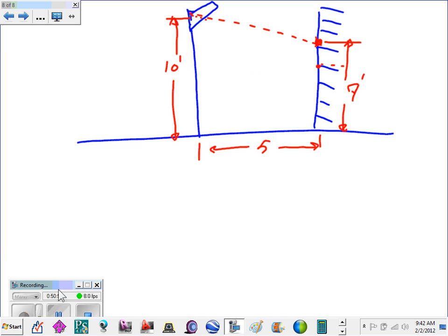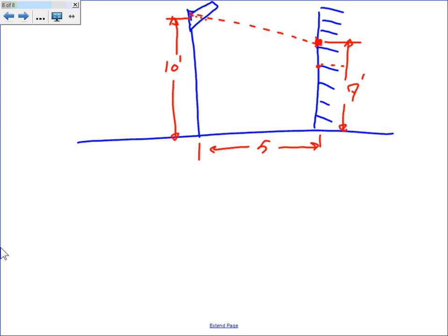For this example, this is the same lighting fixture that we talked about before, the same characteristics, everything is the same, except we have a billboard and we want to light that billboard with this floodlight. The height of the floodlight fixture is 10, and the distance is 5, and I need to find a foot candle at the vertical 0.7. Let me just write the formula here, and then we'll go through the whole spiel.